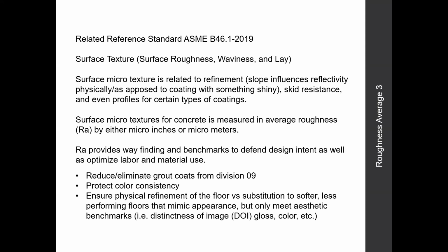And this acts not only as wayfinding for your placement and finishing crews, when can we start, when can we stop, but also we've all been in those situations where maybe you just get that horrible looking cold joint, or maybe somebody didn't do sun and wind protection or something like that, and the texture of that surface suffers from it. Well, in the past, there isn't any benchmark to keep the change orders from happening. It needs to be mitigated, and a lot of times the owner ends up paying for that, or maybe the entire project team dips down into their contingencies instead of the folks that, well, maybe didn't do wind protection, right? So it has a lot of great advantages within the specifications to provide a lot of value.